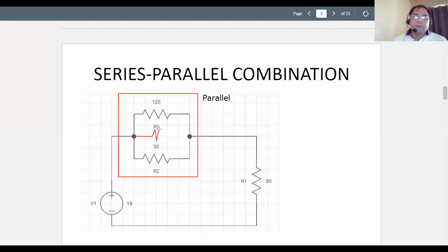Now you combine the two, so you could end up with a single resistance here, which we now call R23, because it's the combination of resistance 2 and 3. So if you are going to disregard the lines above, let's try to cover the resistances. If we combine these two, then we end up with a combined value R23, after removing the individual resistances at the top and bottom.